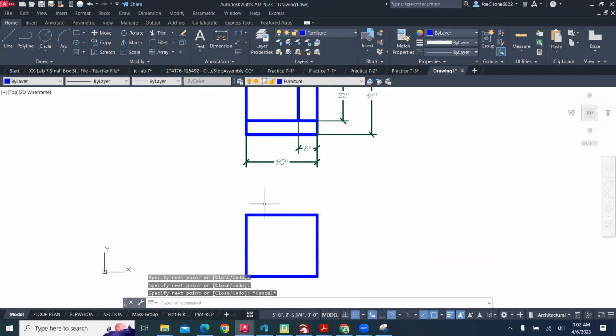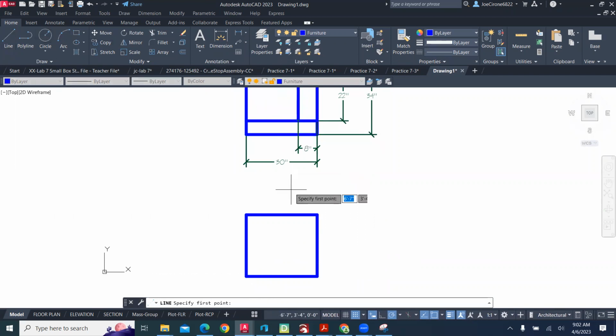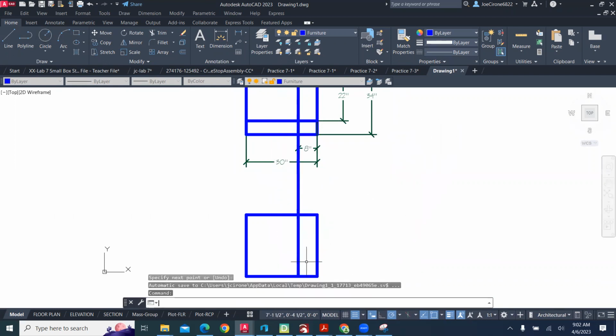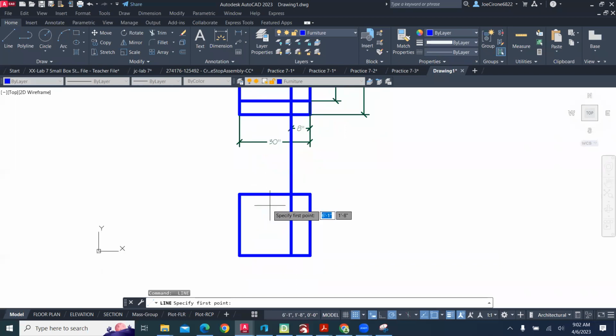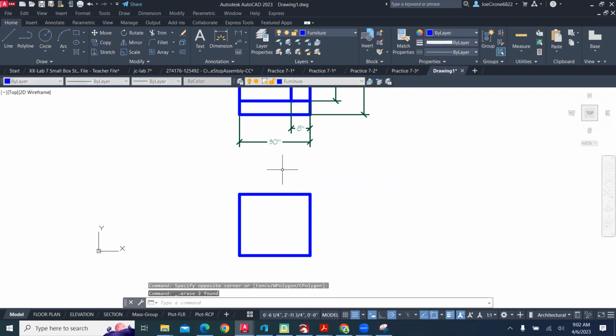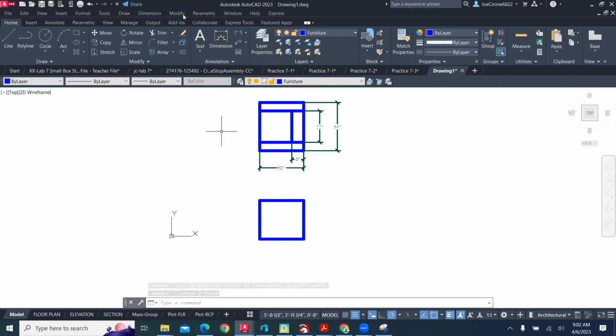And then back to the starting point. And then we'll just offset, or we'll bring these lines down here. If it doesn't grab it, you can just grab it from the top view like I am right here and just trim it. And so that's going to be for the back of the chair. And then actually what I wanted to do was to offset it because it's kind of turned, so that's not correct. And so we're going to offset that to the side. It really should be over here.